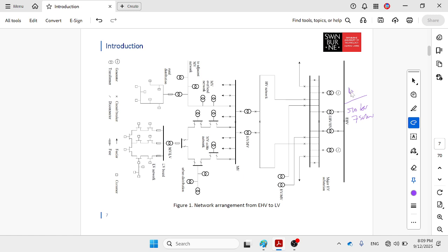This one can be 400 kV also. So step it down to the high voltage. The high voltage is 230 kilovolt. Then this transformer makes it step down again, which can be in Malaysia. I think you have one for 145 kV. In my country it is 132 kV, so different standard. Then another step down transformer is available here, which is close to the city.